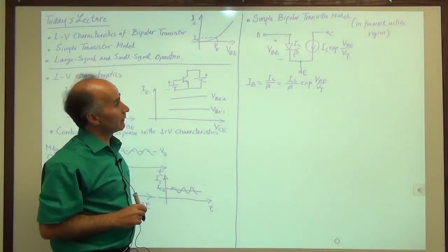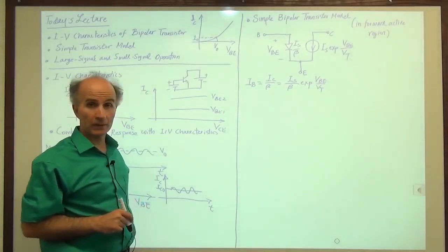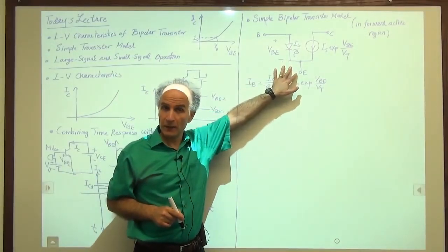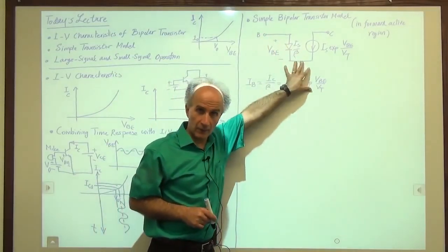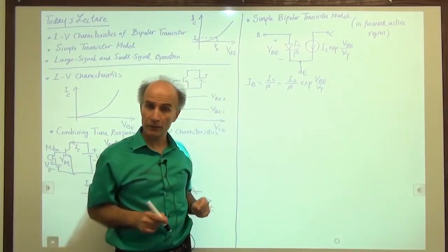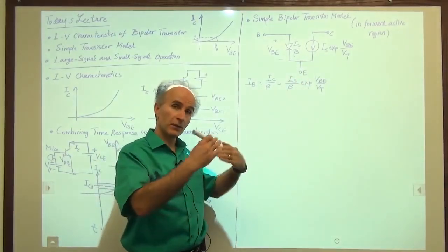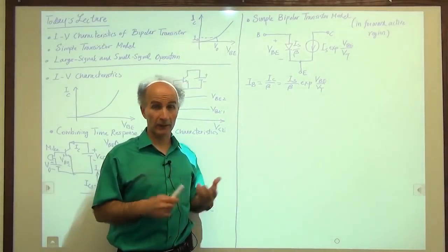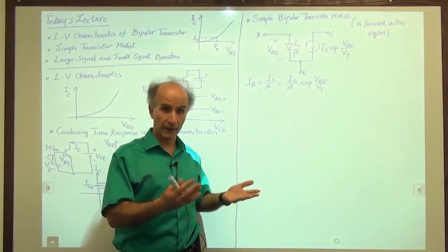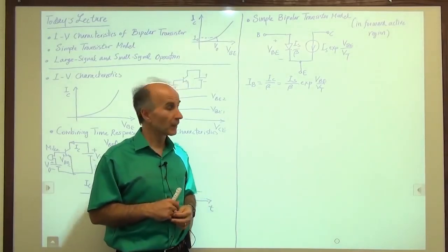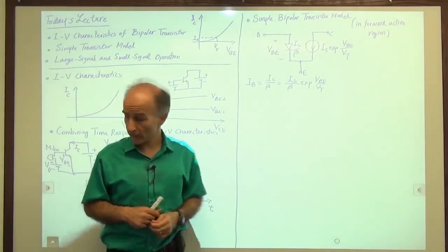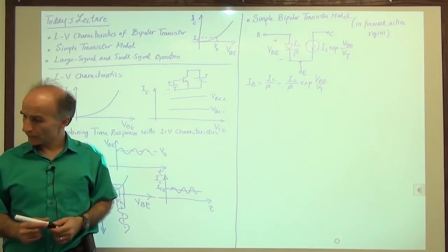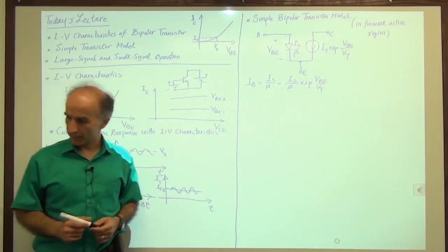Okay, so that's the model that we can use in various calculations. Congratulations. Now, any circuit that I give you that has bipolar transistors in it, you should be able to replace each transistor with this and calculate everything, solve the circuit. Because the circuit now reduces to techniques and topologies that we know from the past, or at least lends itself to simple KVLs and KCLs, etc. All right, that's a good start, and let's start from there and go through some examples to see what happens.